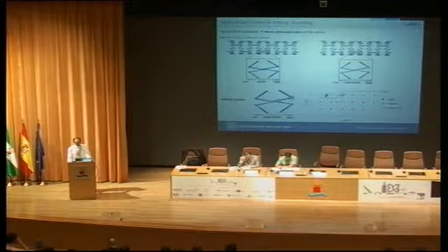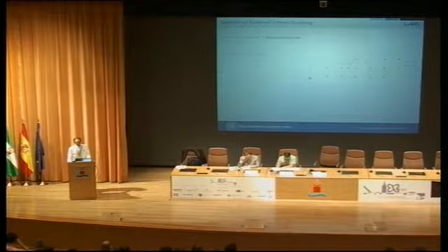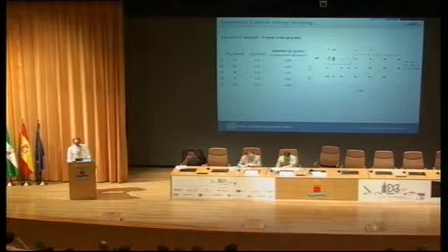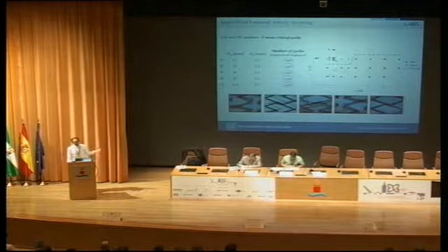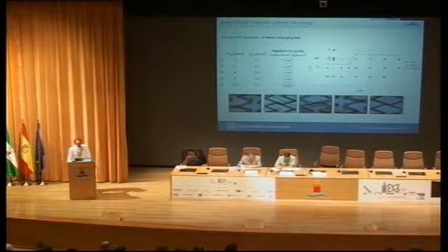So this area, for example, can be plotted in this area, while the strain of this area is located here. So from this graphic, we expect to have fracture here, and we expect not to have any fracture at this point. So the results from these 5 in silico simulations give us this area of most critical point, and we have a confirmation from the experiments that the fracture was identified in those areas.